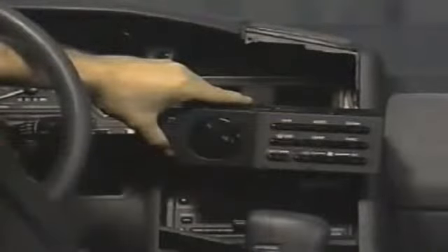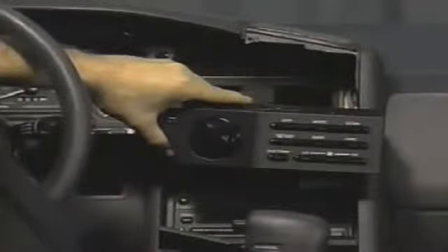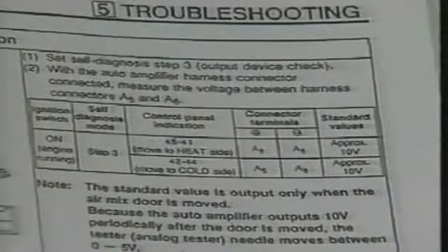The motor drive circuit check should be used if the results of the PBR check were correct, or if the fault code leads to this area. Use the output signal recognition mode to provide a motor output signal. Measure the voltage output of the ECU as indicated in the service manual. Reverse the direction of the motor by selecting the appropriate output signal and verify reversed output voltage. Incorrect readings indicate the ECU is at fault.